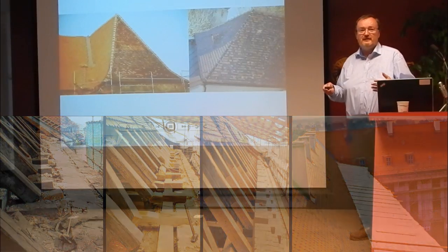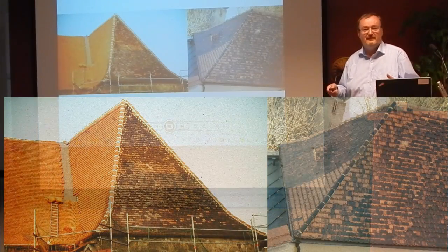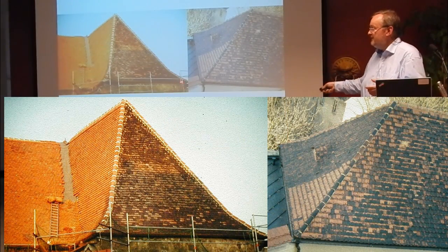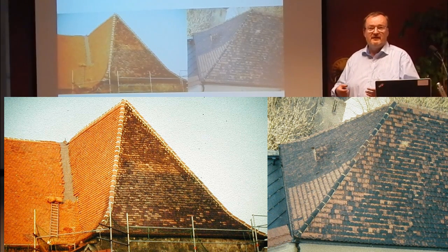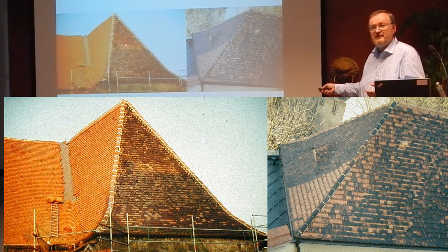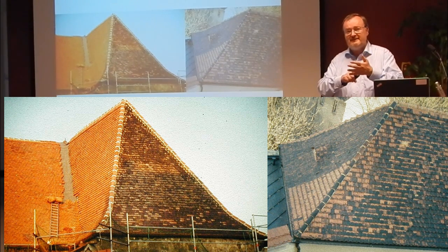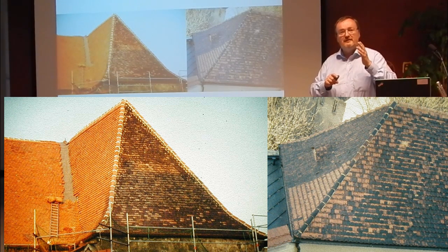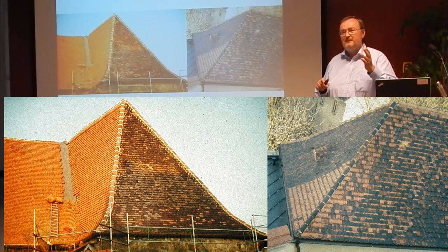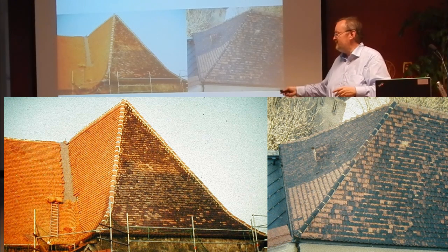I think it's very important to save all what you can find on your old building. And for example, here we have Baroque, so about 300-year-old tiles, and they are damaged in a certain amount, but all which had been good, we have a little hammer, and we hammered on every tile to hear, is it good or is it not good? And all sound material, all material which gives a good sound comes back.